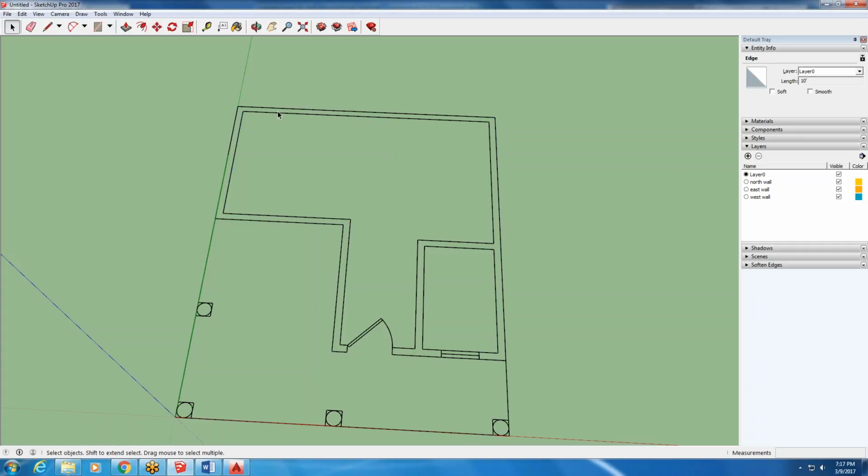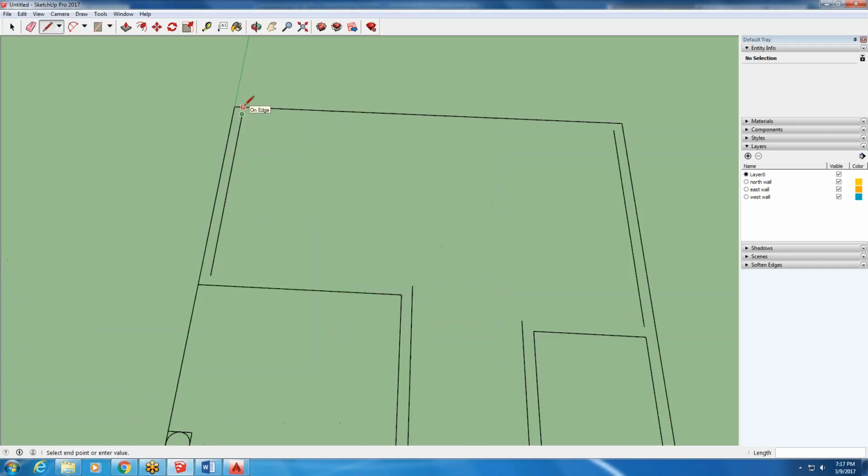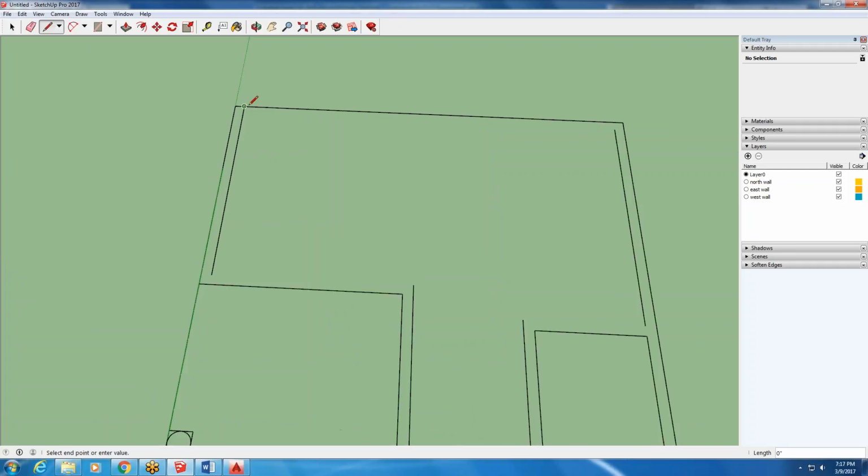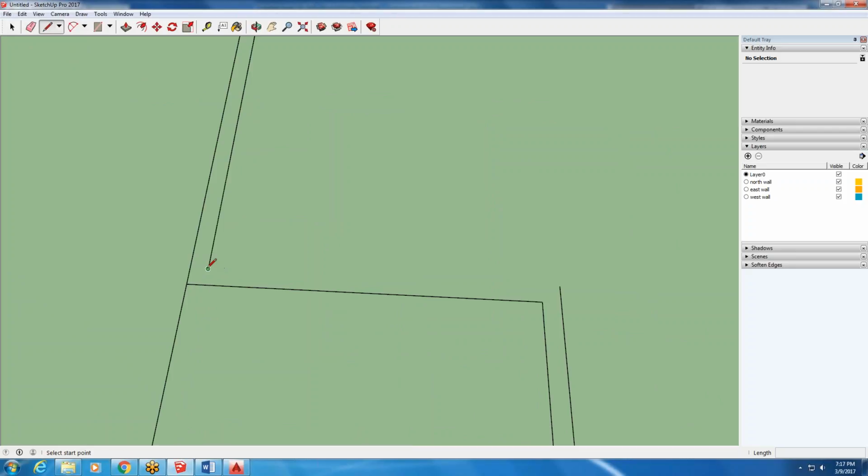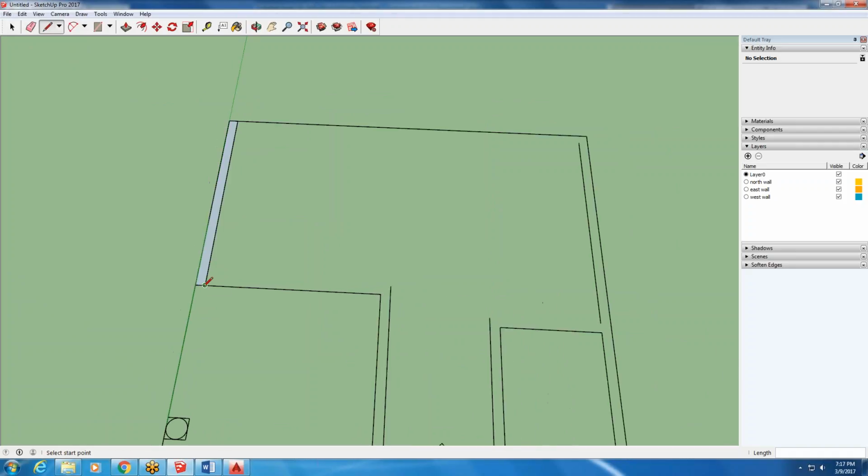So then we had issues with these connecting. You're gonna have to delete something, it's gotta give. So I'm saying delete some of these horizontals out, and then you're gonna click your line tool and continue the lines here. It has to be on the green line, enter, because green goes back. Grab this, click the endpoint, click the wall, green goes forward, and then I'm going to triple click. It wants the whole house. Triple click until it gets just that.